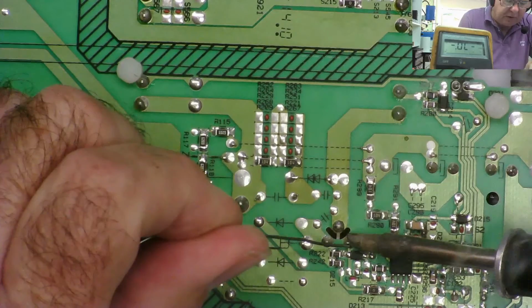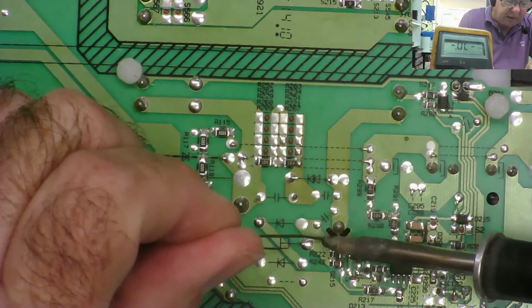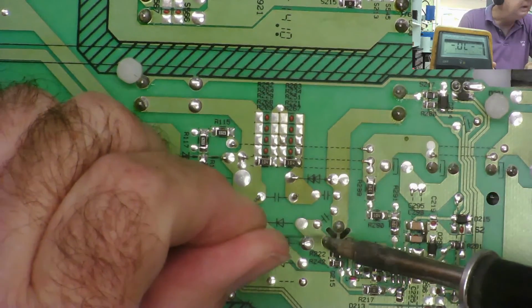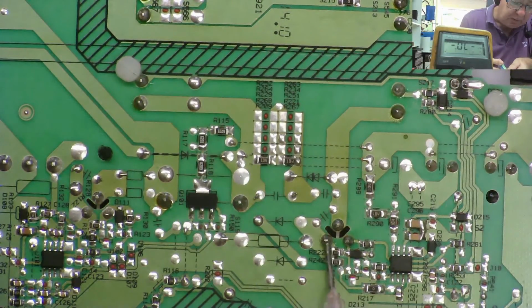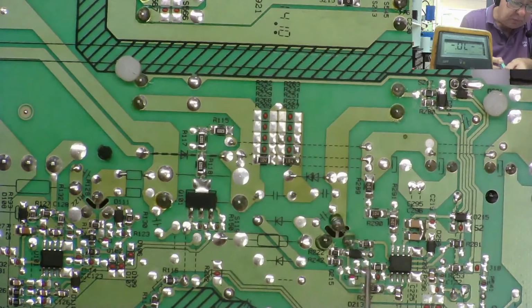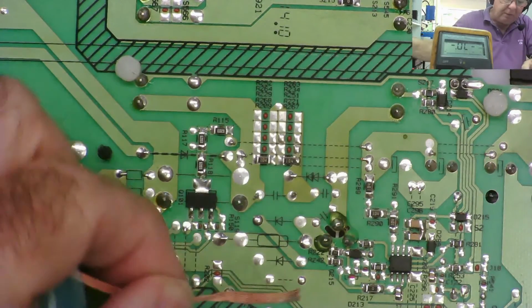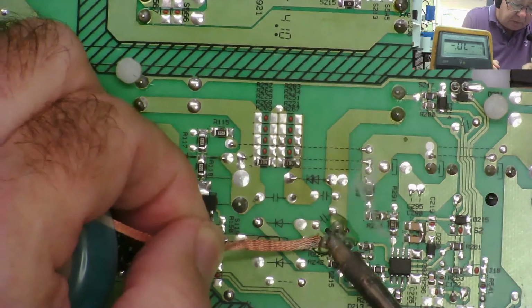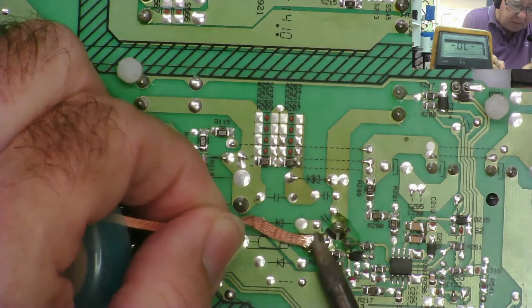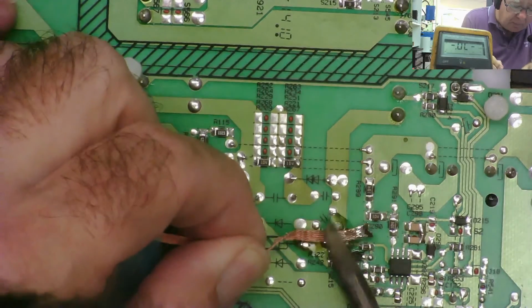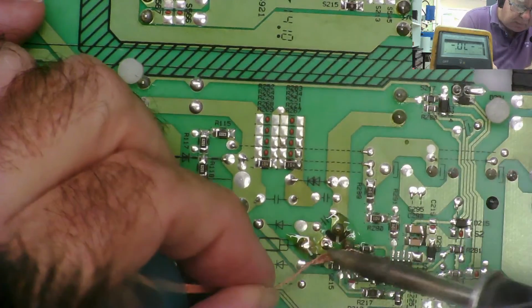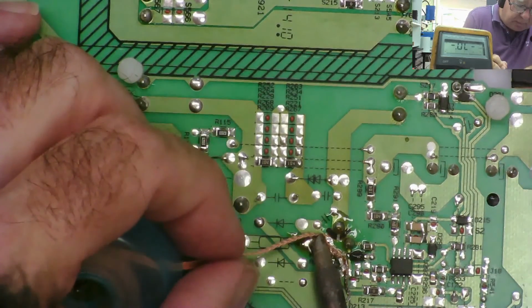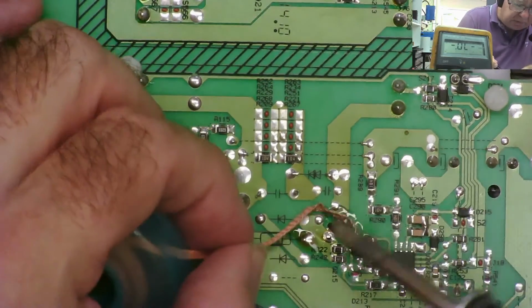So what we do is we stick some solder on each of the pins, a bit of solder on each pin. We'll get the solder flux on there, so a bit of flux, a bit of braid. And we're going to desolder the transistor, but we're not going to remove it, we're just going to desolder at least two pins of it. It can be a little bit tricky. Let's see if we can actually desolder a couple of pins of this transistor.